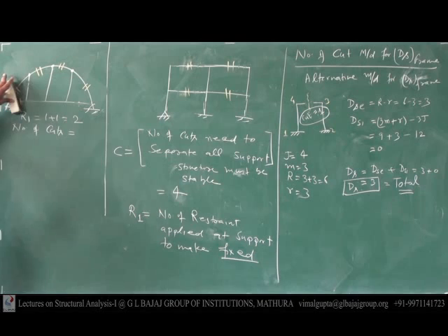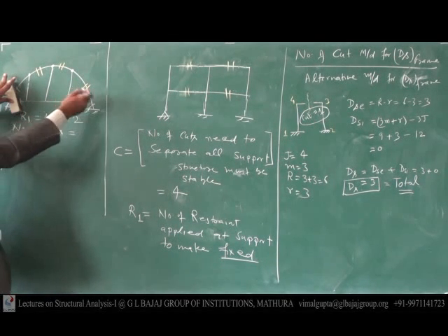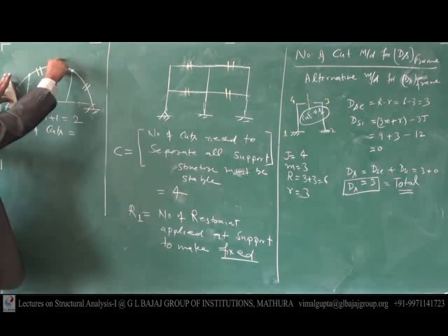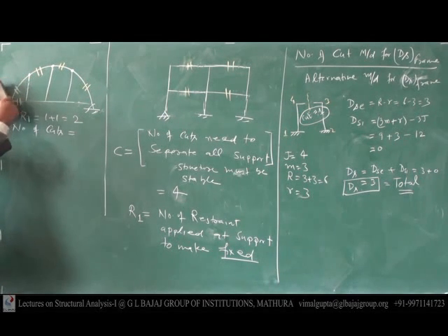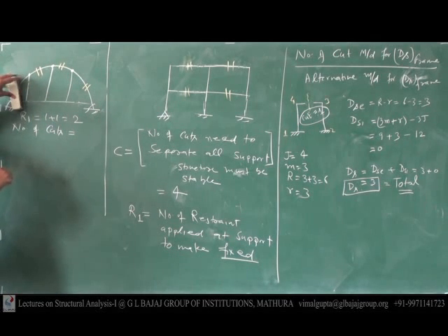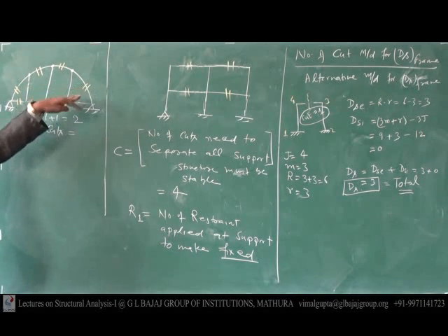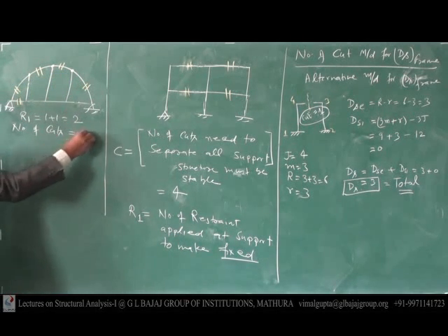To open every joint, what do you need to do? You have to apply the cut over here, over here, and over here. And this one is free from this side, so apply it from here. By providing that, this is also free here. Since this is fixed, the structure will be in a stable condition. So the number of cuts required will be 1, 2, 3, 4, 5.